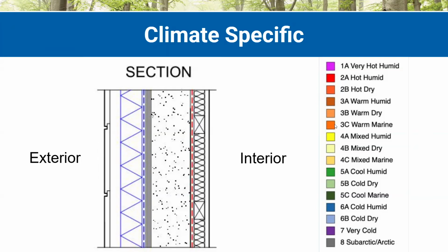For once we're getting into climate zone 4, we're having more robust R value, we're having more real winters. I would now be really prioritizing this interior air barrier. For our humid climate, in terms of climate zone 4A, I still really want a strong exterior air barrier as well. We really do need to air seal both sides of that.